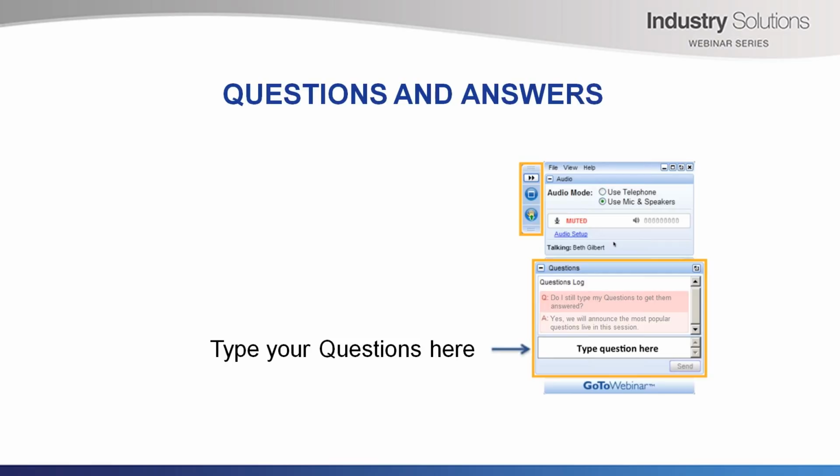And that's where you have to know a little bit about the software package you're going into. One thing that you're all going to find hard to believe, but when you put strings into Solibri, Navisworks, Revit, and whatever, they have to have a diameter. They can't display strings without a diameter. So on our writer, there was a tick there to say, give the thing a diameter. Strings don't have to have a diameter in IFCs, but a lot of these packages are only working as though everything has to be like a physical object. So there are a few little tricks like that as well that you have to know about the packages you're going to. And say Navisworks, it looks like you have to pre-calculate some of these attributes, but the attribute manipulator will do it for you.